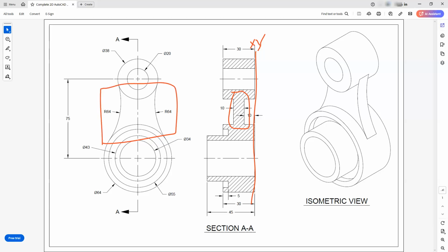If I'm trying to create that, I can't put it on this plane. If I do, when I create that shape, it'll be sitting down here. Now, there are some other options I can do. I can probably use an asymmetric or something of that nature. But what I like to do is go ahead and try to assign a plane to it. If I assign a plane to that, then it makes it a lot easier when I go to put this stuff together. That means that I can control this middle portion by this plane. Meaning that if this distance changed to 5, I can simply tell that new plane that I create, hey, make that distance 5. So that's what I'm going to do.